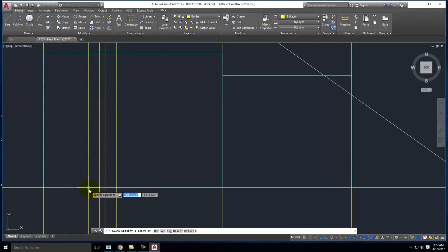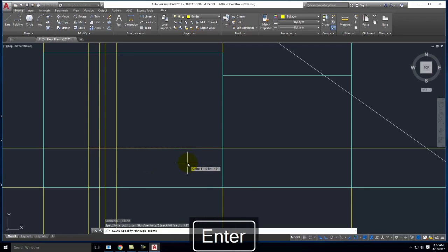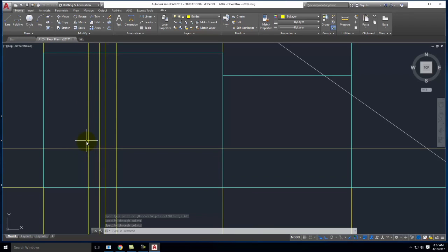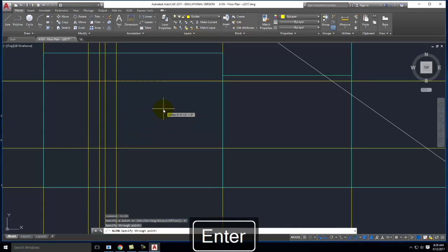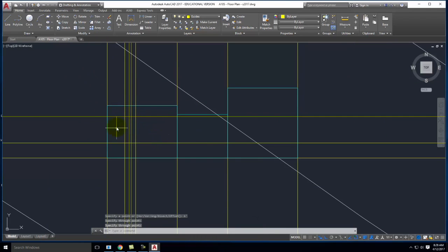And we'll start that construction line up 42 inches from the ground, like that. And like I said, this is a very tall building, so maybe I want tall windows. So from the window, maybe I'll have 6-foot high windows, and that gives me the top of my window. And so I've done all of those as construction lines. If we were drafting, these would be just light lines. And now it's time to add some detail to them.